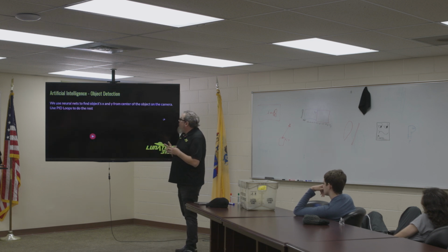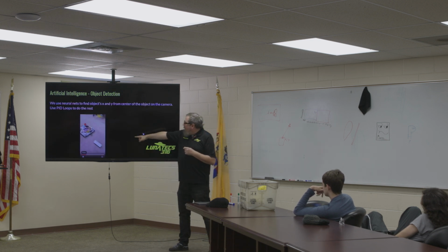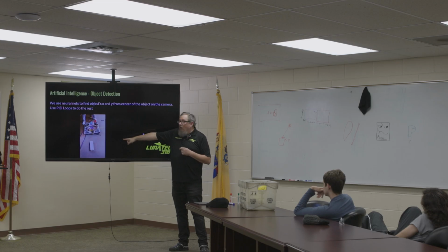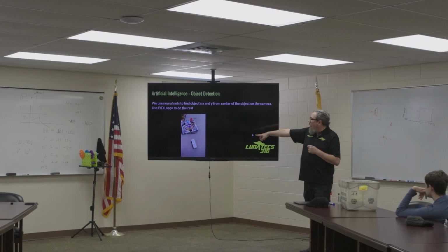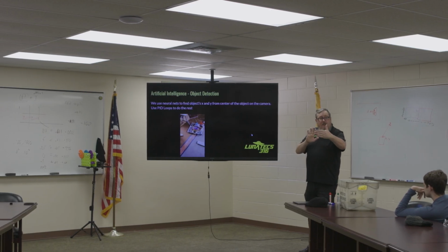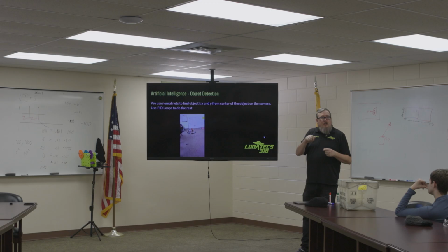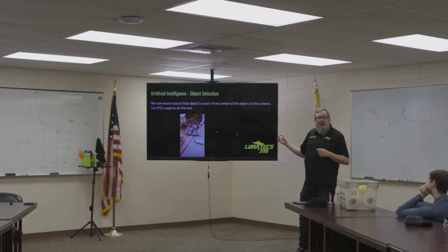So by using a PID loop, knowing how far off-center it is, we can track coral. Did you see how that happened? It found it and then just started following it. And we said, hey, follow at a distance of 1 foot. Don't touch it, just follow it at 1 foot. So that is algae tracking.